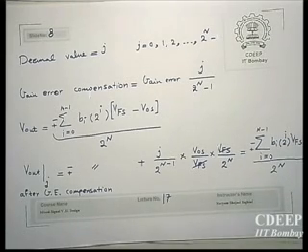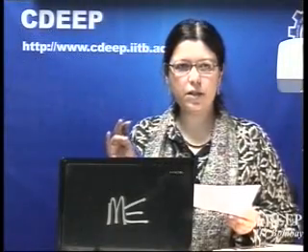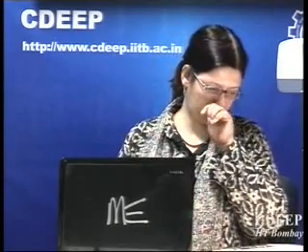So after all, the whole story is, if op-amp offset is constant, there will be gain error and offset error, and both can be compensated. Even if you don't compensate for gain error, what you will get at the output will be only a scaled version of the signal.